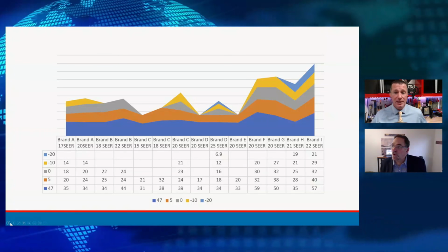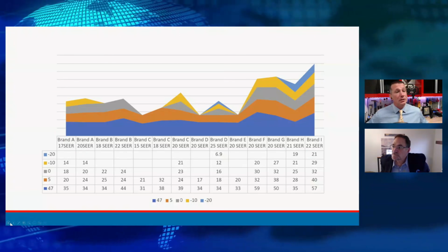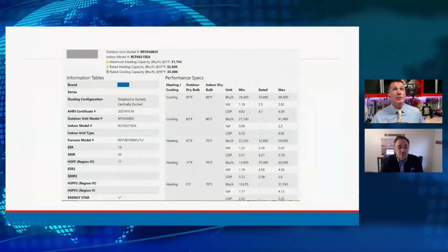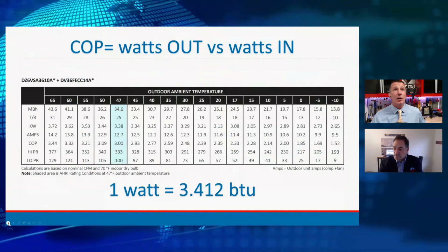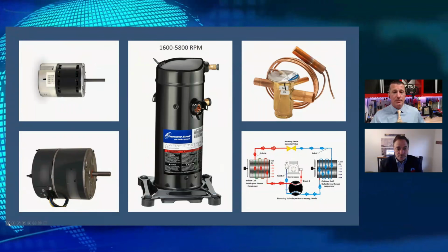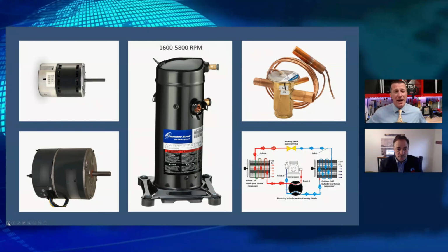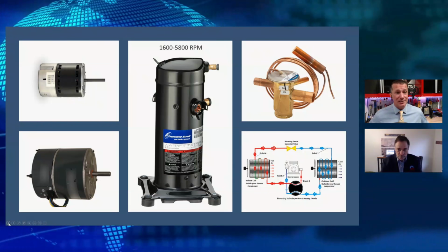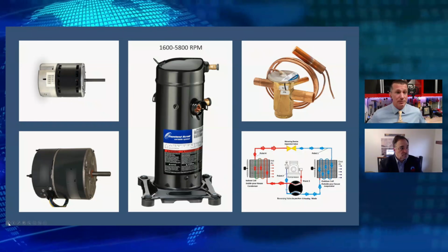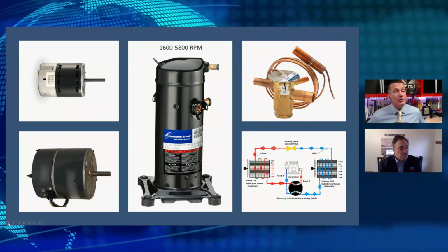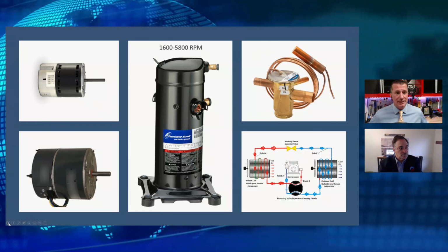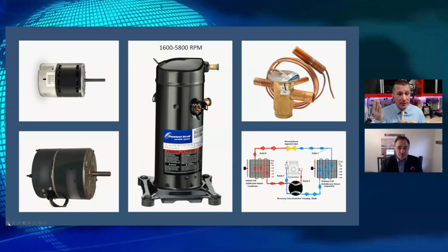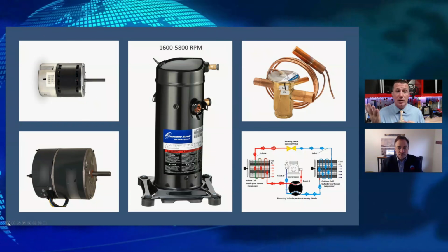So, Mr. Beck, is a multi-stage inverter really a true inverter? Well, let's think about that. When we were looking at the different parts that go into a system, and we talked about the evolution of heat pumps, along the way, about the middle way, we went from permanent split capacitor motors in our compressors to ECM-style motors. The earlier generations of those were multi-speed ECM. So we could have a multi-speed ECM indoor fan motor. We could have a multi-speed ECM outdoor fan motor. Neither one of them true variable speed.